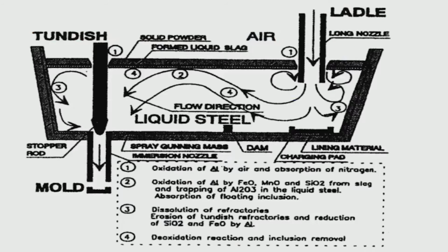Yesterday in the last session I had just started talking about what a tundish is, what happens in the tundish, what the issues are, and how we have to be careful during casting, so that there is no exogenous entrapment from the tundish. So, this is liquid steel coming from the ladle. I was talking of the refractory nozzle, the refractory shroud, and we must use some argon also here, so that there is no air ingress here.